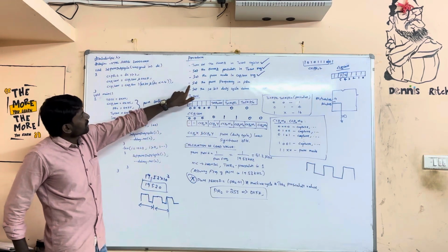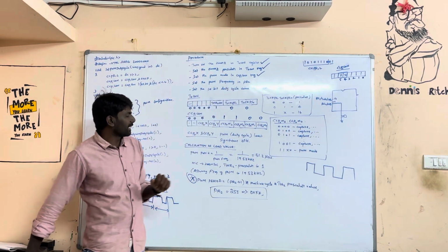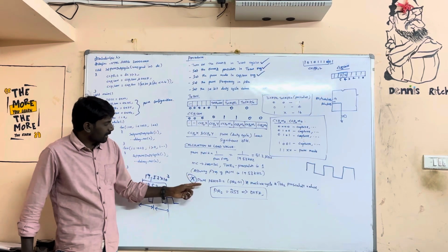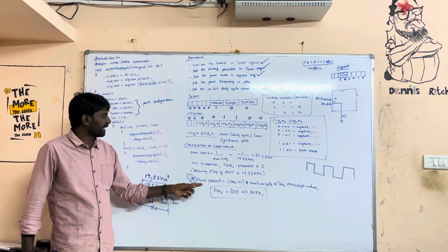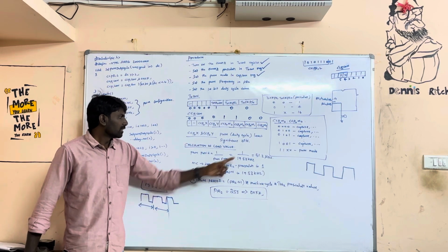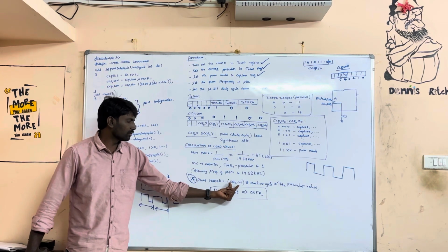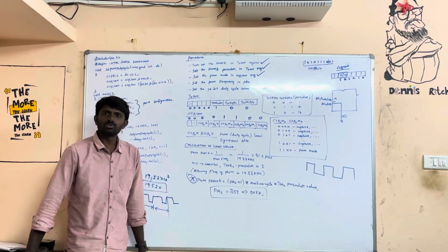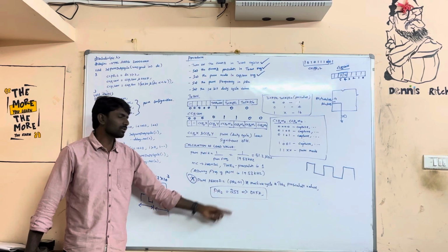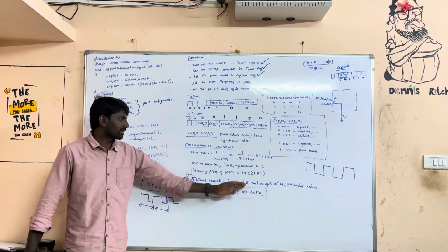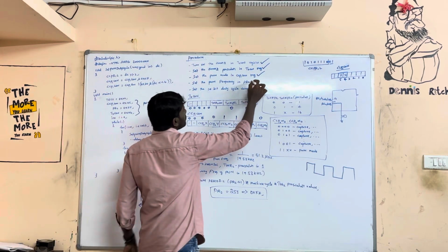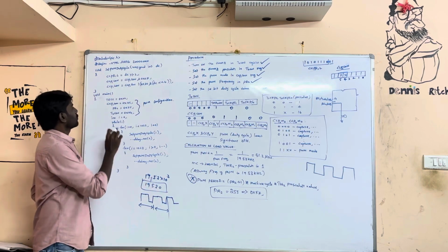Okay. The third step is setting the PWM frequency in PR2. You cannot set it directly, so there is a formula. In this formula, you calculate the PWM period using the frequency. You substitute that here. PR2 we don't know; machine cycle and prescaler are substituted. So finally the only unknown value is PR2, which you generate. PR2 has become 255, which in hexadecimal is FF. That is the fourth step we are setting here.